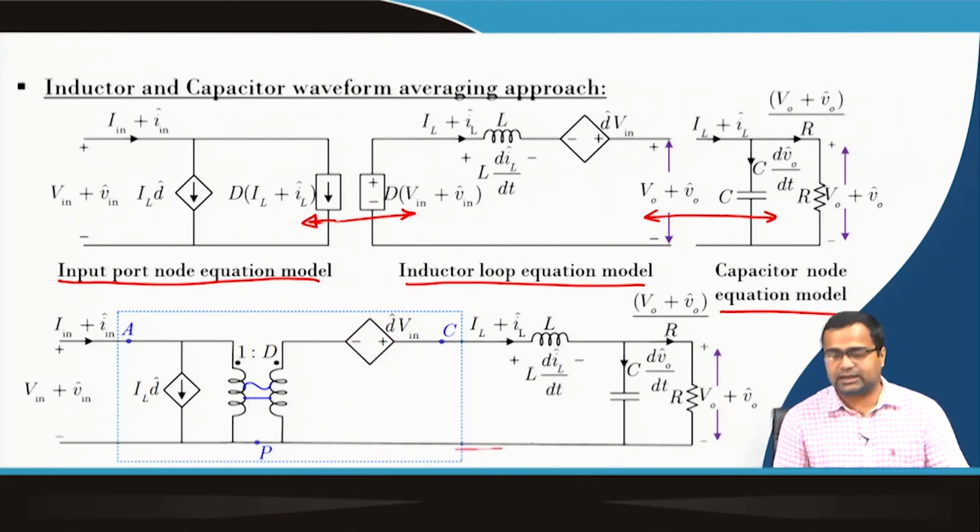Okay. So, the equivalent circuit model can be obtained either by applying the average switch model, that means the 3 terminal switch model, or you can obtain it by individually considering each waveform and its sub interval equations and then averaging out, to obtain the dynamics of the variable that we are interested in.